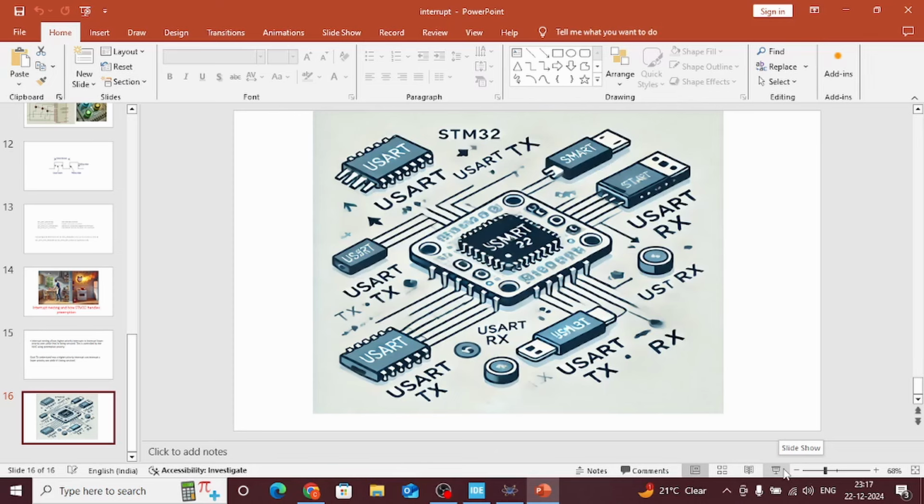However, here USART is there, but the normal full form of UART is Universal Asynchronous Receiver Transmitter. Asynchronous means that there is no synchronization between the transmitter and receiver. Now what is synchronization? Synchronization means the receiver can understand where to start and where to stop. Let us say the transmitter is trying to send a 1111 message, so four times 1 in binary form. How will the receiver understand that there are four ones, and where to stop and where to start?